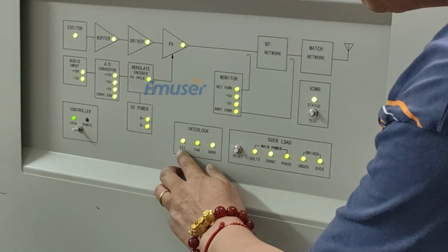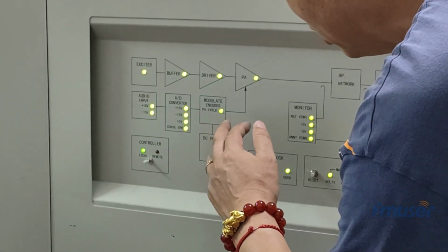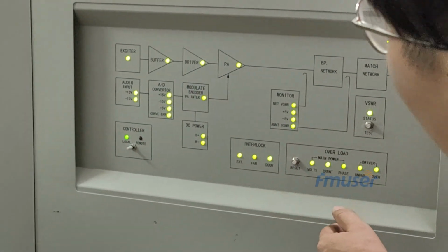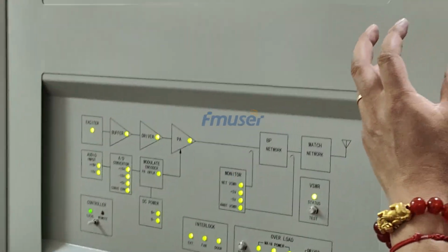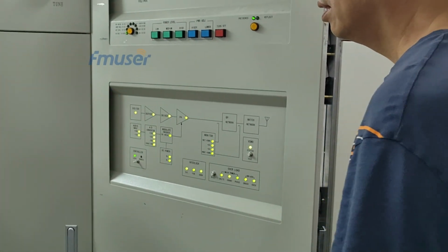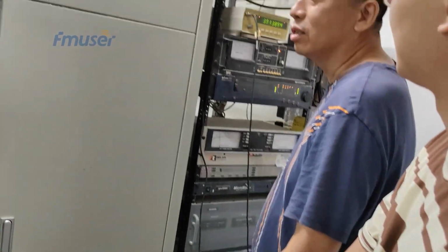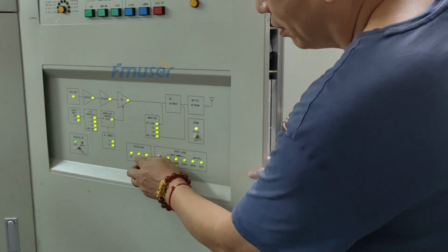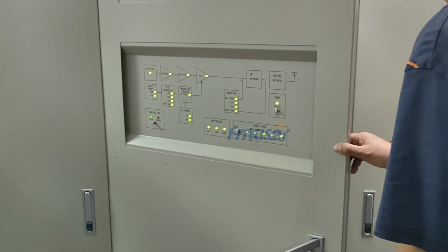We have the EXT indicator, which stands for exterior, referring to the external devices connected to the transmitter. The EXT external device indicator light serves the purpose of detecting the presence of the ground signal and indicating the normal functioning of the equipment connected to the transmitter. For instance, if the transmitter is connected to a load, such as a dummy load, and it becomes overheated or is not switched on, a signal will be sent to the transmitter. As a result, the EXT indicator light will turn red, indicating an alarm situation.